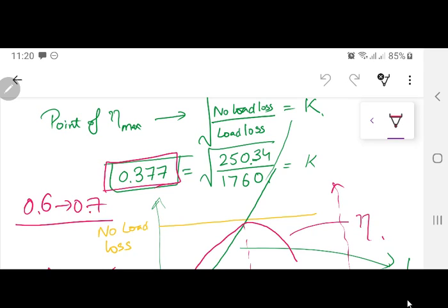In the 2013 session when I taught this course, I did a 630 kVA transformer. This time I have changed it to 100 kVA. Go through chapter number 6 yourself. It's the same thing. The only change is that the size of the transformer will be large, the window height will be large, the winding ratings will be large, or the capacity will be large, the current density will be different, and we have designed an aluminium transformer. In 630 kVA, you are designing a copper transformer.